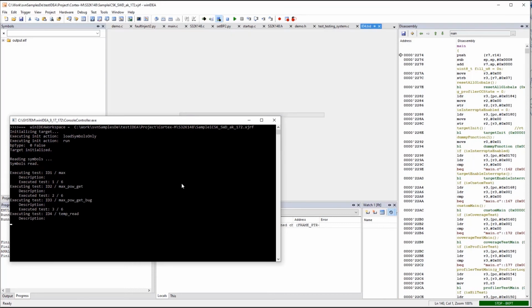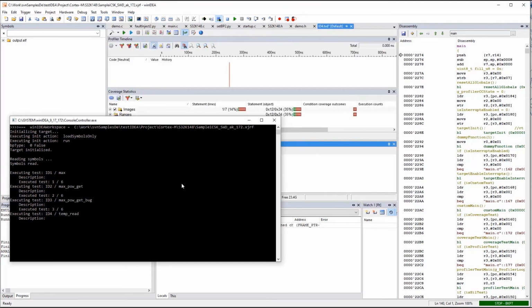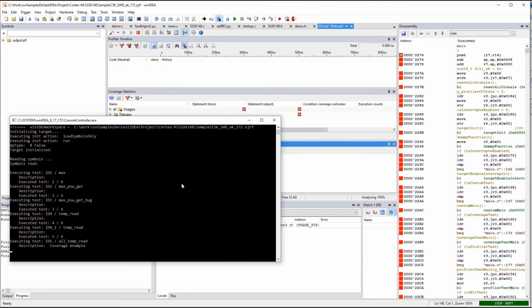So it shows how you can automate all of the test functionality. You can use the testIDEA GUI to create the test scripts if you'd like, and then generate the test script and modify how the test script executes. You can add functionality to it that way. Maybe include some other tools like dSPACE can also be controlled, or other kinds of HIL or IO tools can be controlled with the same Python script.